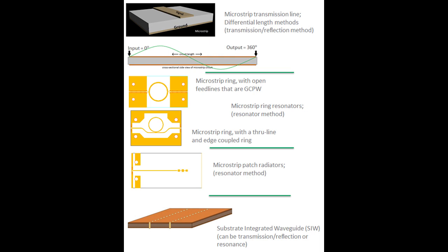So with this differential length method, where we have circuits of 2 different lengths, we are able to extract what the dielectric constant is by knowing physically what the difference is of these circuits. So that's one test method. And that's actually the test vehicle that we use most often for the microstrip differential phase length method. That test method is what we use to determine the design Dk that you see on our data sheets and product selector guide.